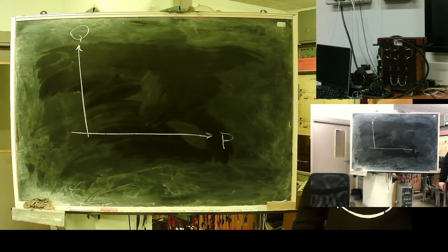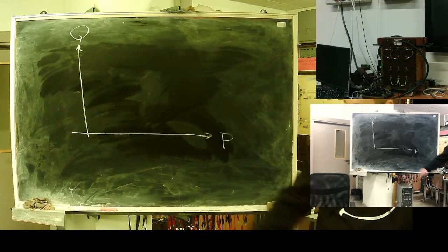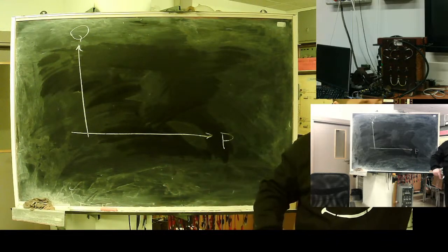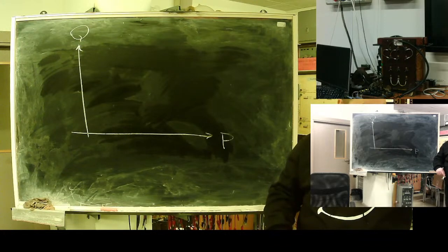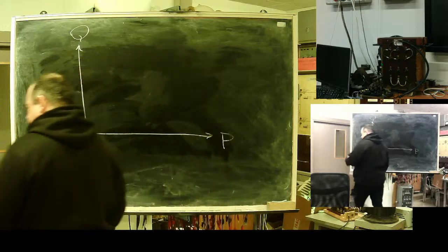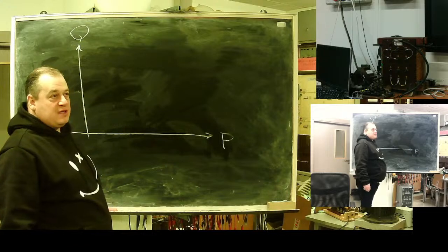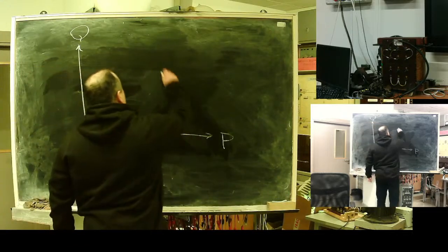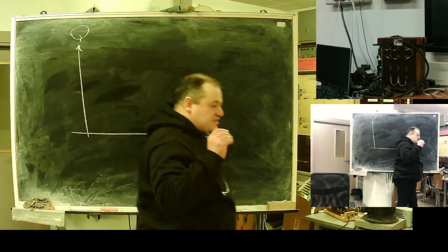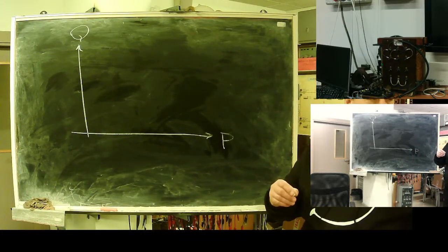I can choose more. There is a problem. This power plant may be more effective than that one, but the transfer losses I need to cover equalize them. So I can write an energy balance equation here. One of the stations will perform a balancing role. It will be the selected bus.